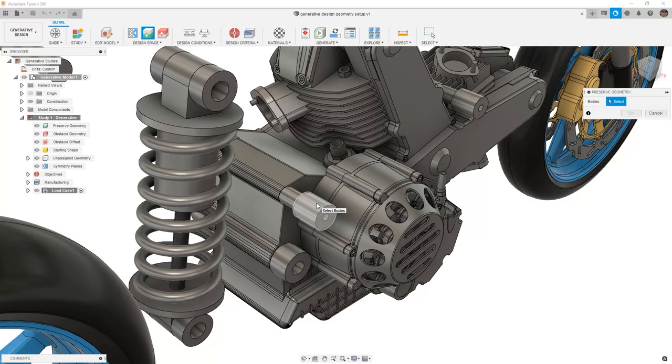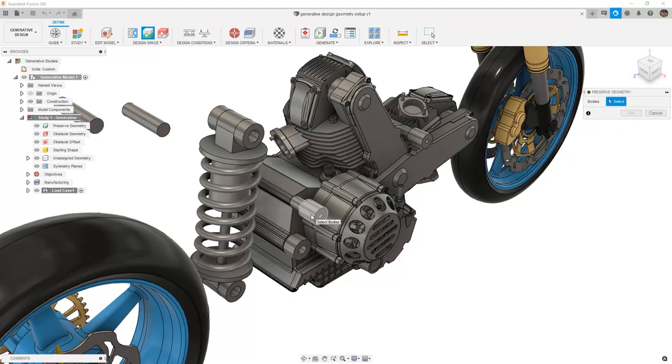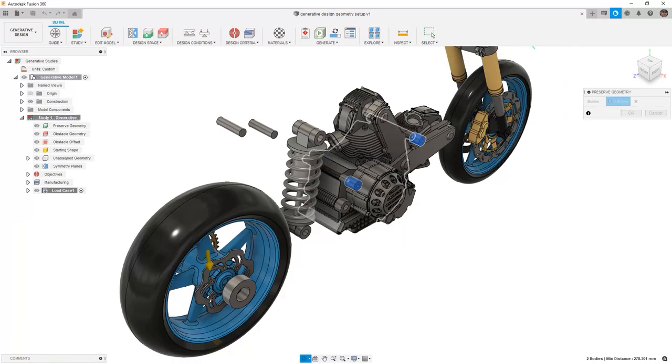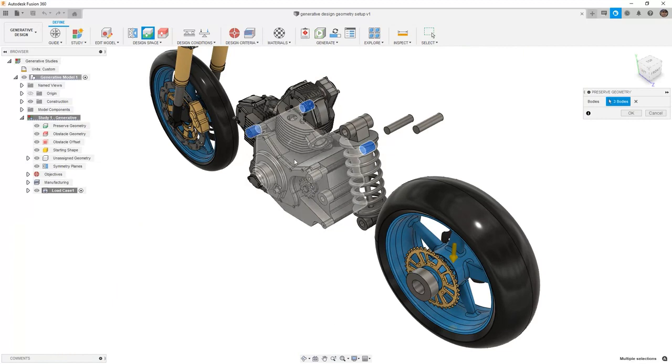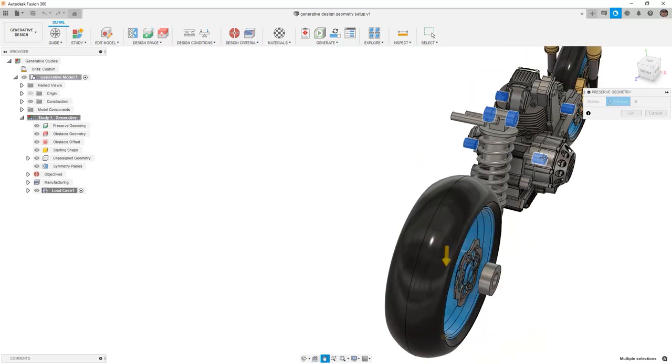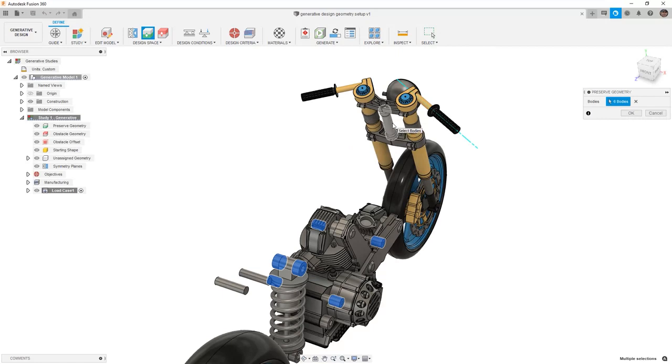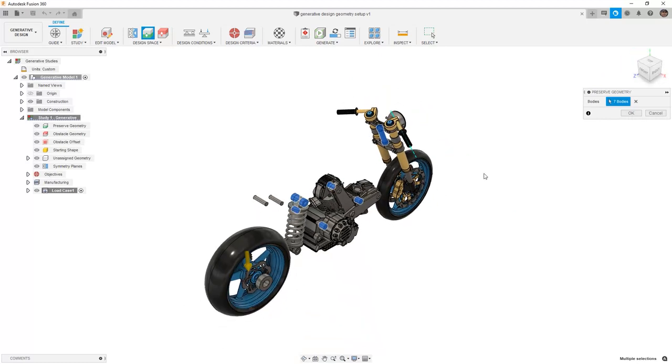In this case, it is important to note that with this Ducati engine, it is a structural member. So we're simply going to mount the frame to these 4 spots on the motor. We're going to rotate this around. And then the ones down here are actually for the swing arm on the rear. We also need to include the upper mounts for the suspension. And then we want to move on to the front, and we want to include the outside portion of the steering stem. These are going to be the elements that we're going to use to generate our frame.